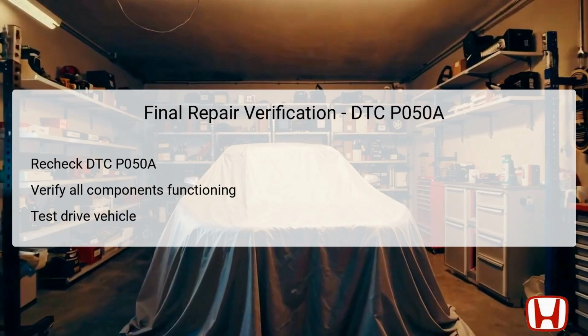Ensuring that all components involved, such as the throttle body, MAP sensor, and IAT sensor, are functioning optimally is critical for proper engine performance. It's also beneficial to perform a test drive to observe how the vehicle operates under real-world conditions. Monitoring for any warning lights and checking engine performance during the test drive can highlight any remaining issues. By verifying that the DTC has cleared and performance is normal, technicians can ensure that repairs were effectively executed.